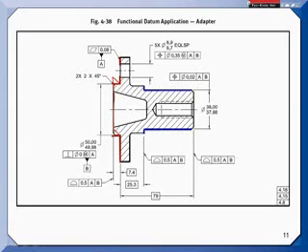And remember, this is going into a mating part where this acts bigger now with respect to A. Its size, and I exaggerated, is good. There's its size. But its virtual size might not be good enough to fit the mating part. And so it might even start to go into the mating part, but then as you try to bolt down and make full contact on A, you're straining the part.